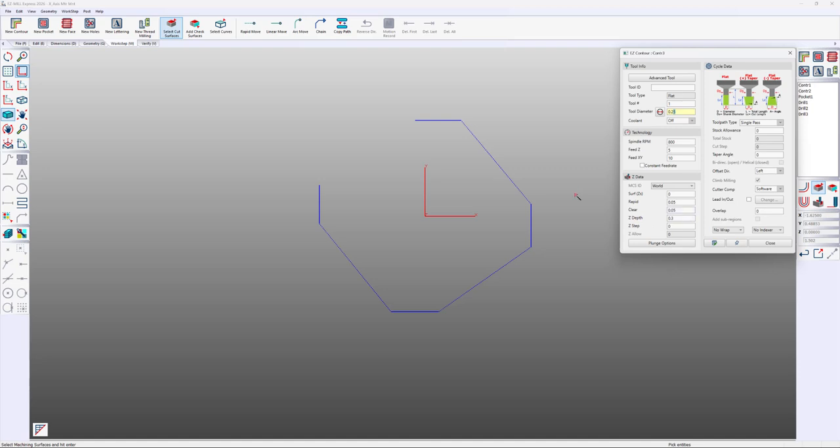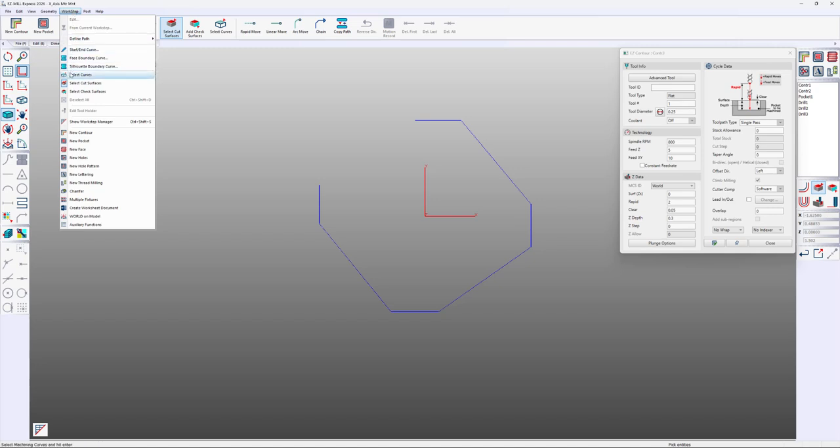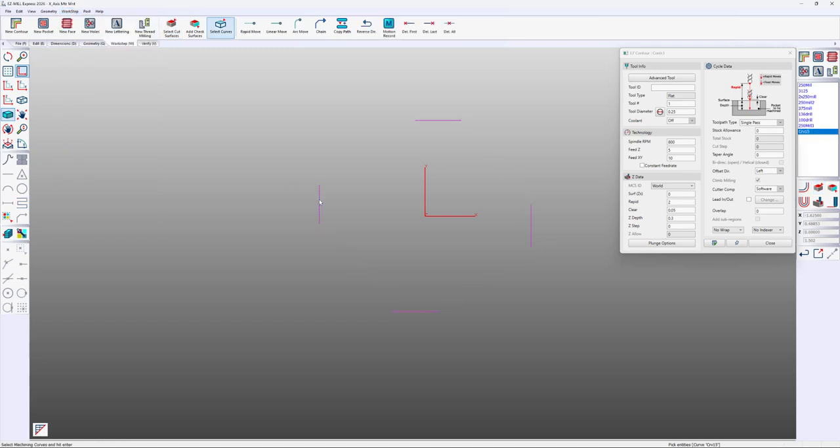At this time you would reposition your clamps to clamp the actual part itself, and you would adjust your rapid to go over those clamps, so 2 inches above. I would have done that with the other operations as well. So now we're going to go to work step, select curves, and we're going to add that to this operation. Verify.